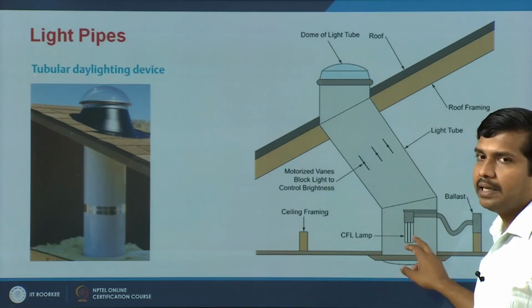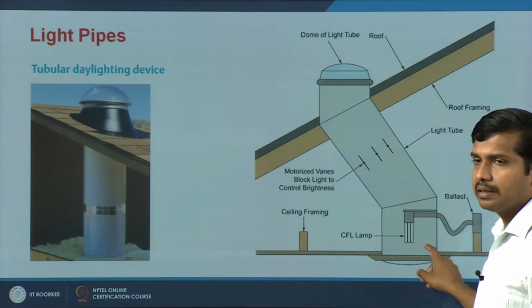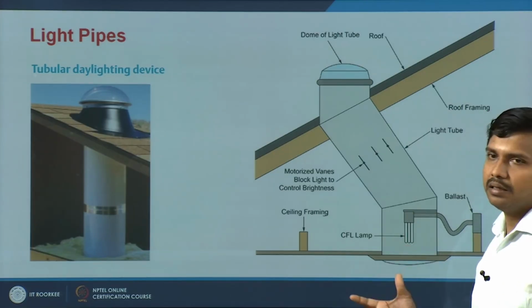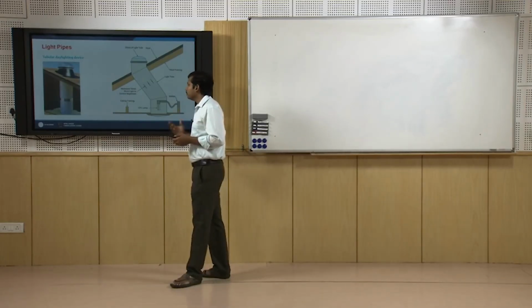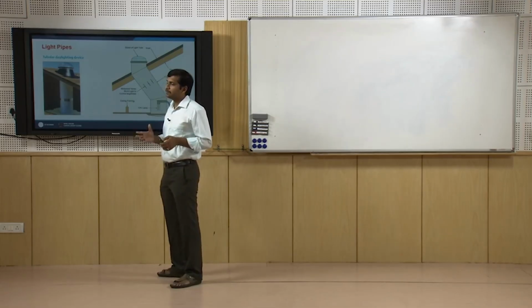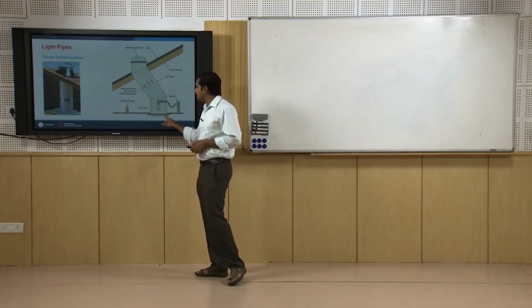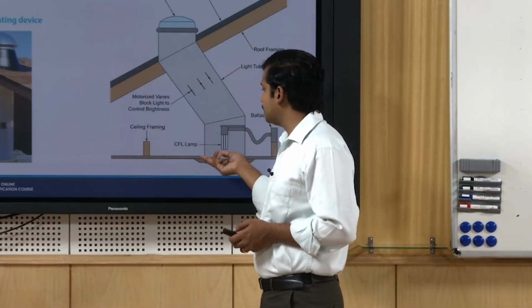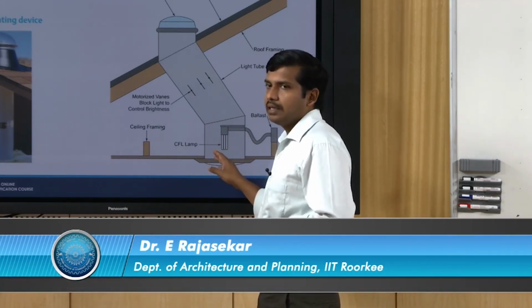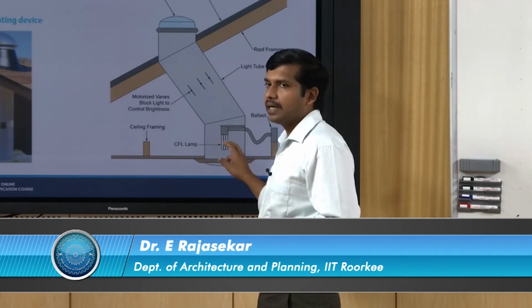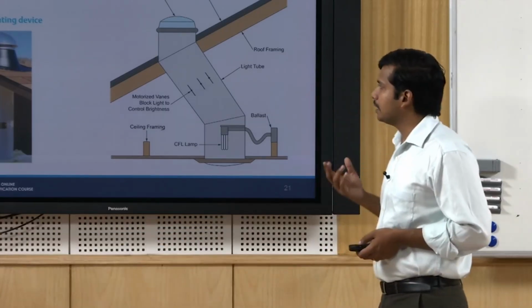This supplementary lighting, there will be a sensor which measures the amount of light which is getting through. If the light levels are lesser, this will be actuated, this light will supplement the amount, so that interior suddenly do not turn darker and you do not lose vision in that case particularly. For example, you have a basement parking, you definitely need specific set of backup lights. There should be a sensor and actuator mechanism which will sense the amount of light coming in, it will actuate the artificial light. So whenever there is a less amount of light which is received, this will get activated and you will have artificial light, interior light levels or lux levels does not get drastically affected.